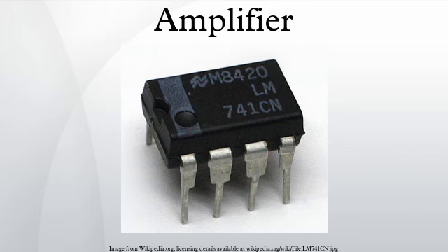The signal bandwidth of the amplifier is limited by the Q factor of the tuned circuit, but this is not a serious limitation. Any residual harmonics can be removed using a further filter. In practical Class C amplifiers, a tuned load is invariably used. In one common arrangement, the resistor shown in the circuit above is replaced with a parallel tuned circuit consisting of an inductor and capacitor in parallel, whose components are chosen to resonate at the frequency of the input signal.